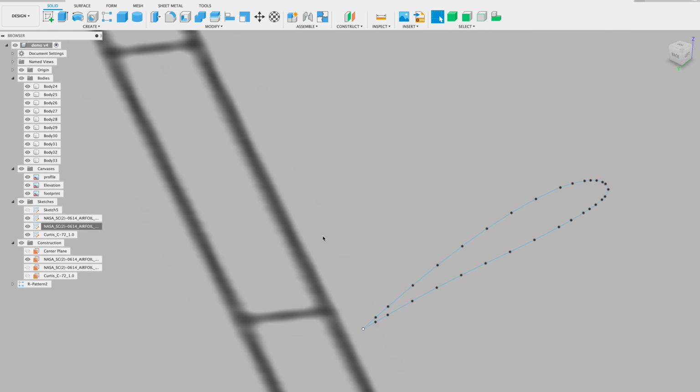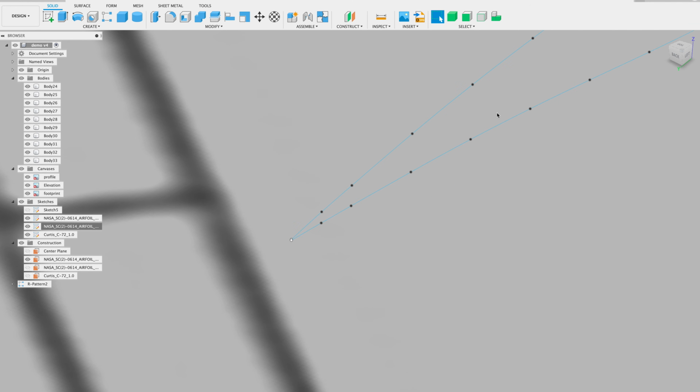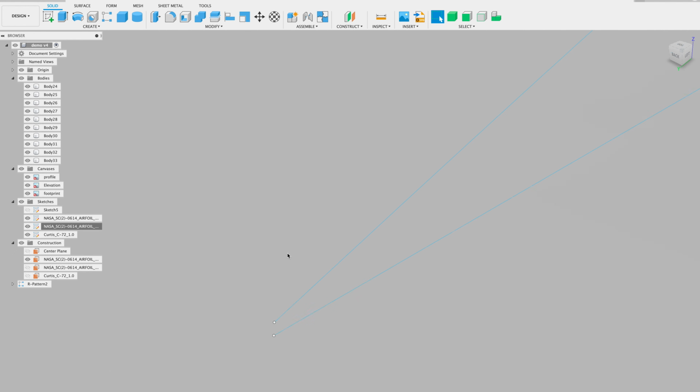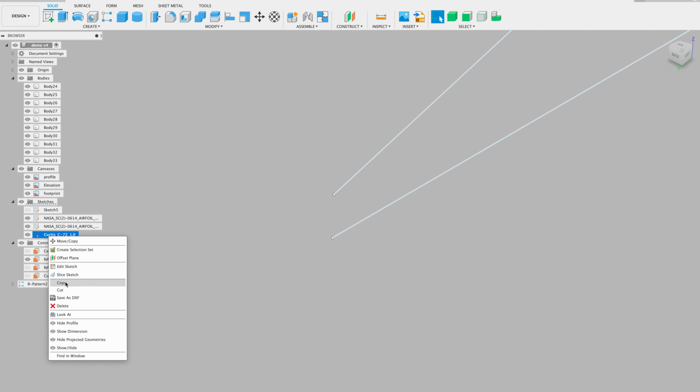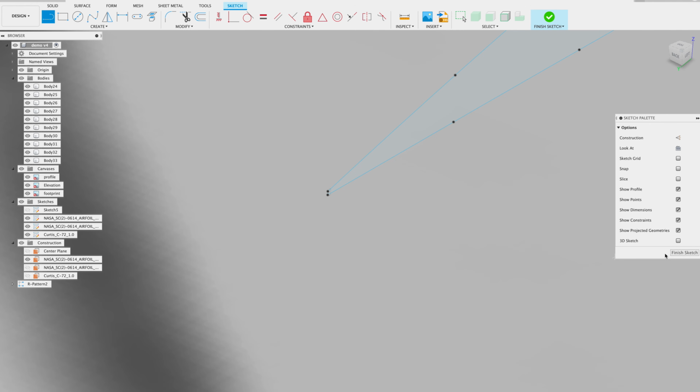this right here, very end. Now it looks like it's connected, but as you can see, it's not filled in. And you can look here, it just barely connects. So we're zooming way in. And again, we're going to select, right click, edit sketch. We're going to use our line tool, come in here, wait till we get the square, select, drag down, select, and once again, we are filled in.